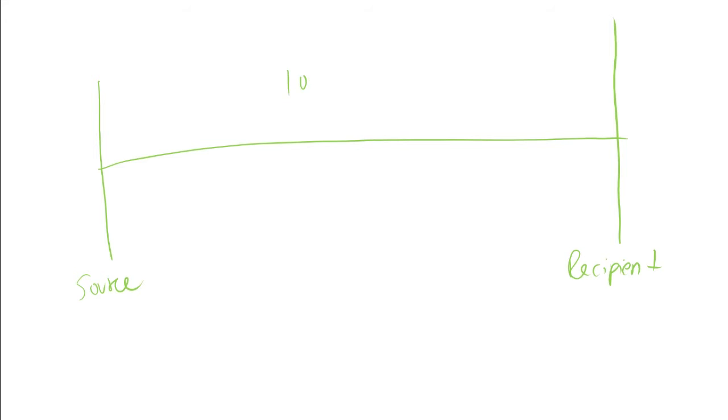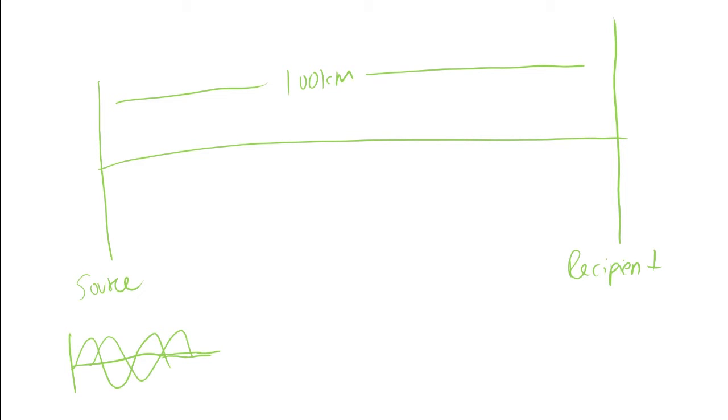Let's say this is 100 kilometers between the two phones. We're going to have some distortions. Remember, we're transmitting on a sinusoidal frequency, and what tends to happen is we have a phase shift. And so this phase shift can distort the signal. And part of it is due to the resistance of the wire.